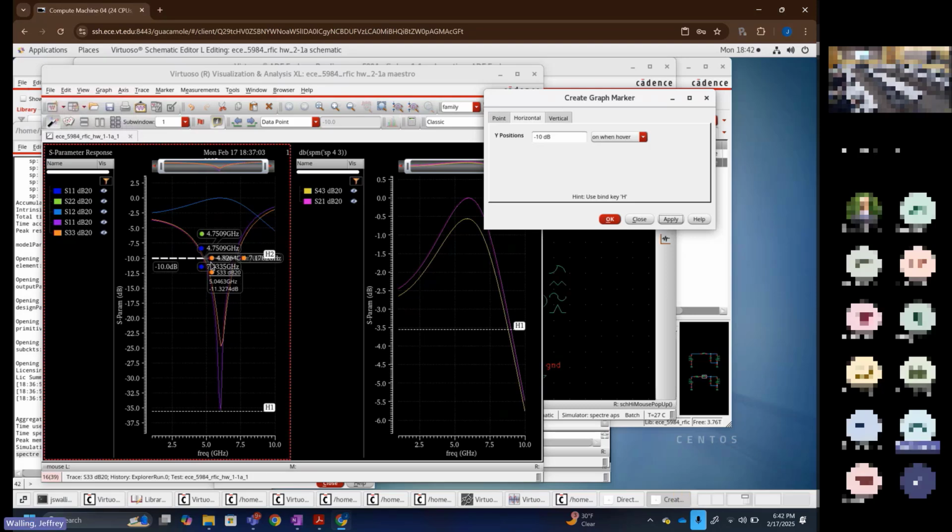The reflection coefficient bandwidth of the circuit and the transmission coefficient, which would correspond to S21, don't always correspond to one another. The way that the resonances work, sometimes you have gain or at least lower loss across a different bandwidth than your impedance match is good. Okay, any questions on the mechanics of these simulations or anything like that? Okay, not hearing any.